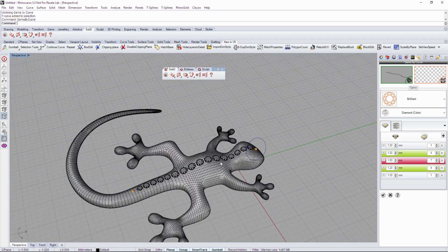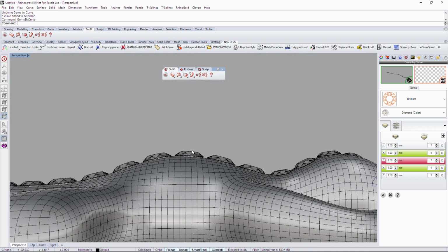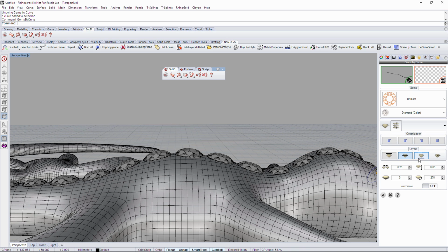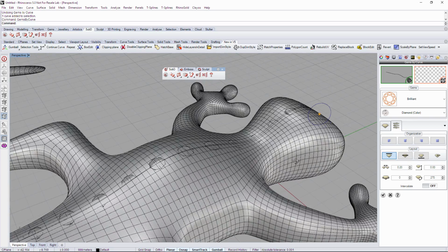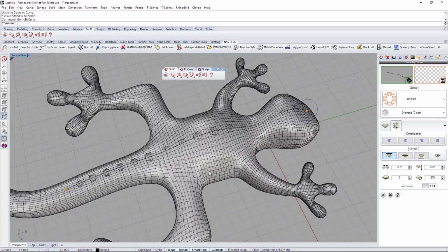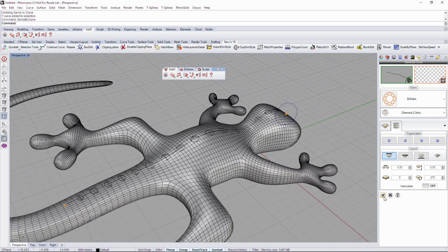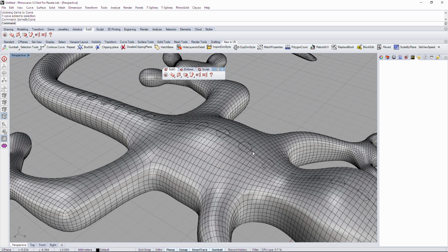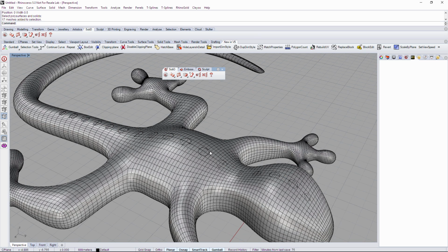Okay, that's quite good. So we want the gems just to be on the bottom part of the object, so the curve to be at the top. So let's go to properties and not center, so the curves will be on the top. Okay, something like this. So just to make sure that they are inside the object. And now we can apply the cutter on it. Okay, so now we're gonna validate. Okay, now we have our curve, our gems. We can get rid of the curve, so maybe we're gonna hide that. So now we have the geometry and the gems.